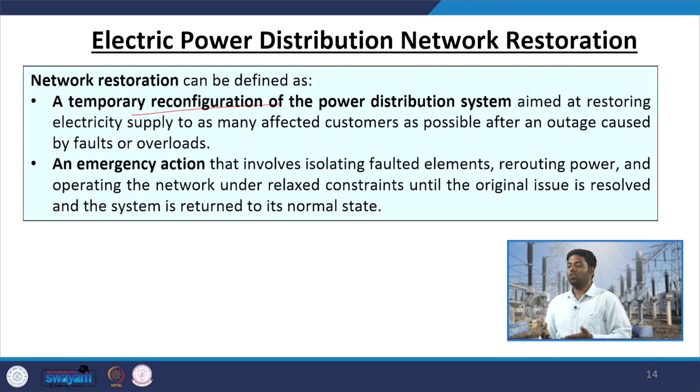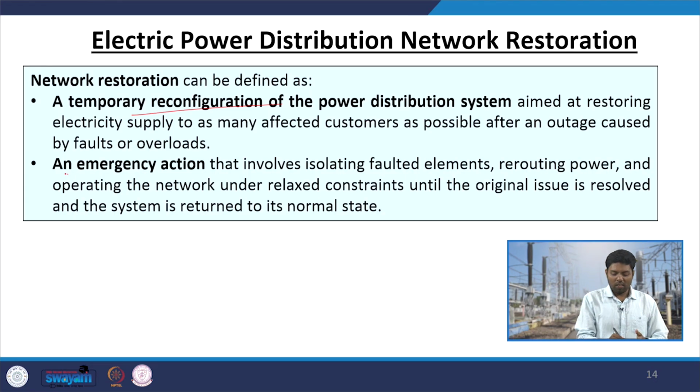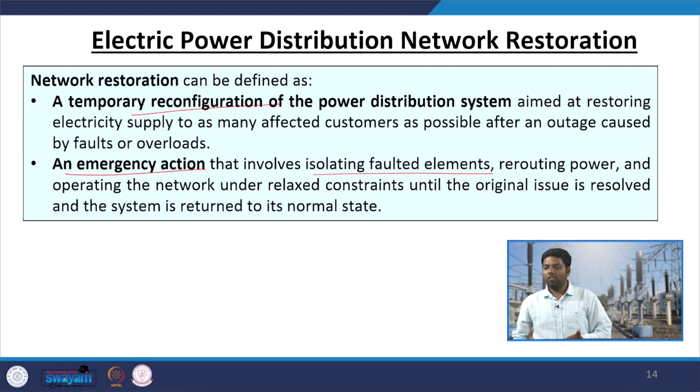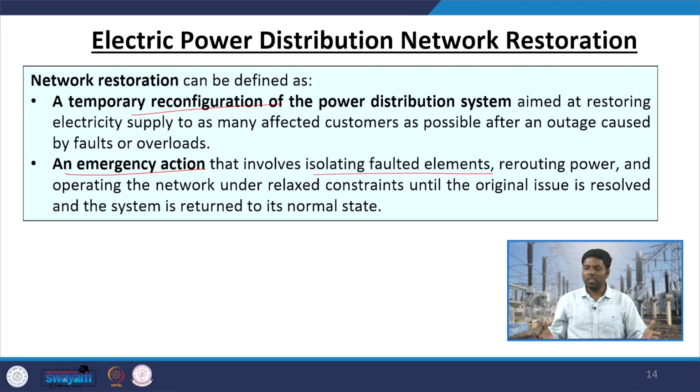Whenever you need, those paths are not economic, those paths are not loss minimized, and they will not give you the lowest electricity bill or energy cost, but at least they will help you cater to your far end loads with an alternative energy path. So, that is a temporary solution that you can take immediately, because restoration, that is the emergency actions or isolating the fault currents, to completely restore the service by fixing all the damages will take time, a few hours, sometimes a few days.